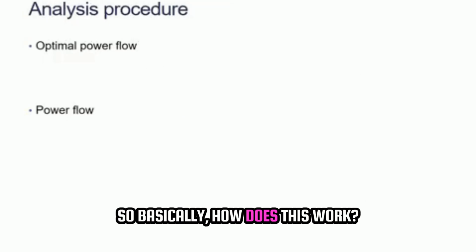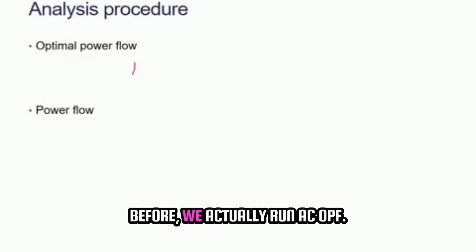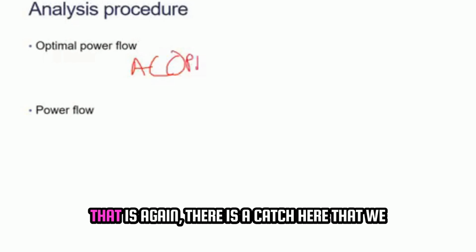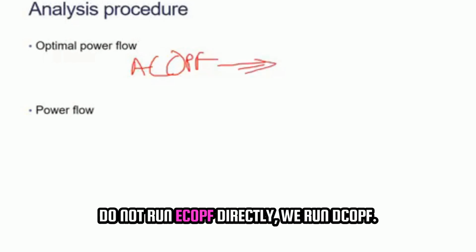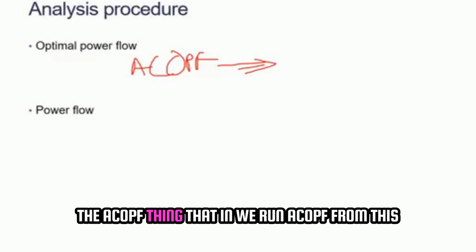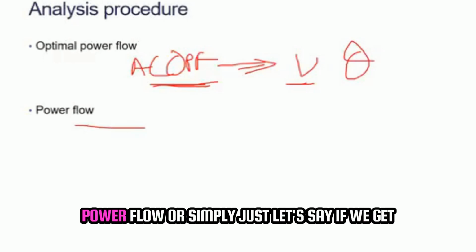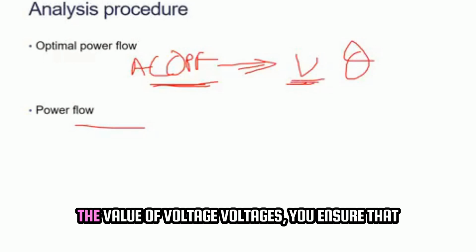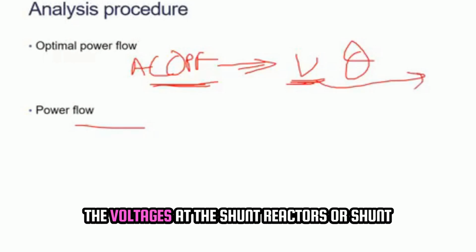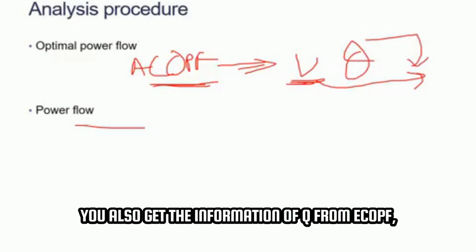So basically, how does this complete reactive power thing work? As I have told you before, we actually run AC OPF. Again, there is a catch here, that we do not run AC OPF directly. We run DC OPF, but just for simplicity, let us go with the AC OPF. From this AC OPF, we get the values of voltages and Q, and we run a power flow, or simply, if we get the value of voltages, you ensure that the voltages at the shunt reactors, shunt capacitors or SVCs are maintained. So you also get the information of Q from ACOPF.